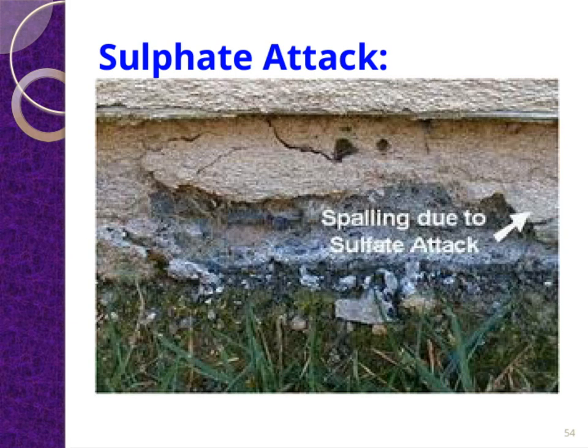Sulfate attack is a common form of deterioration that we see in concrete structures, especially those exposed to aggressive environments. It occurs when sulfates penetrate the concrete and react with components within the cement paste, leading to expansion and cracking. This process can significantly weaken the structural integrity over time. The key point to remember is that sulfates come from sources like soil, water, or even seawater, and their presence can be quite insidious because they're often hidden within the environment.